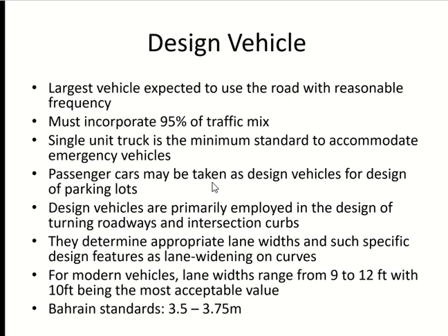The minimum design standard for any road is a single unit truck, which is the same size as an emergency vehicle. What is an emergency vehicle? Which one is called an emergency vehicle? Ambulance, fire trucks, even dump trucks. These are all emergency vehicles. This is the minimum. Parking lots can be designed for the size of a car. Parking lots are not designed for emergency vehicles.